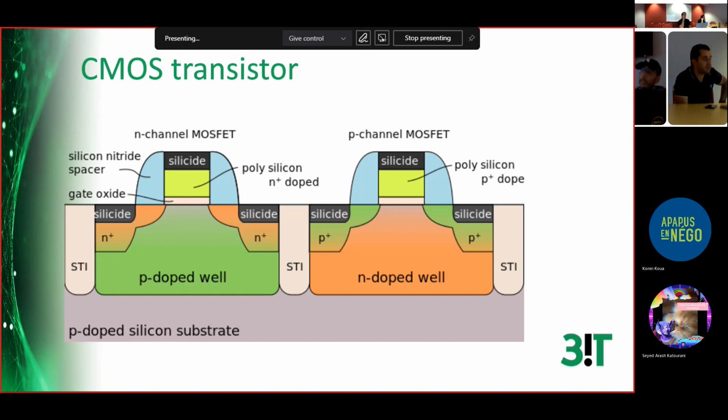Between dummy and the real device, it has to be the same active region, a continuous doping region. When you add dummy, let's say you have your real device here, and you have many fingers of this one. Let's say you have one device of 2 fingers, right?